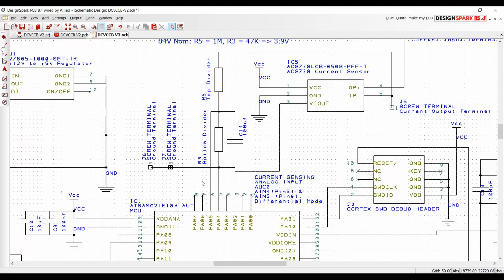But as you can see, Atmel Start really doesn't give me a good way to do that. Now, in software, I've done some experiments where I try and use the underlying API to flip between the 2 modes. Single-ended analog input read on this pin, read it, and then quickly change to a differential read between these 2 pins, and then read it.